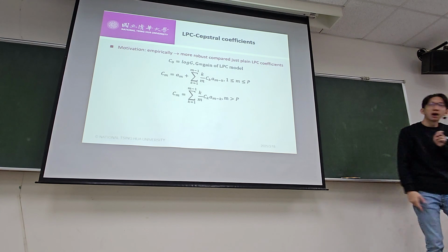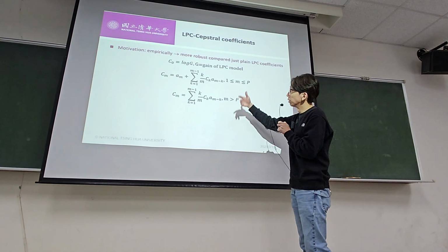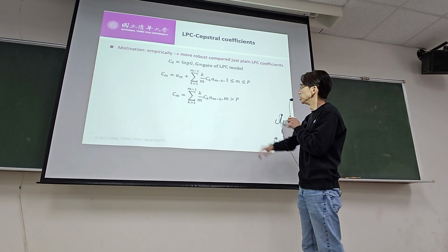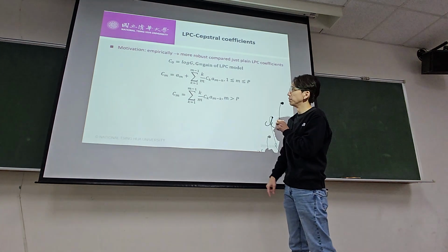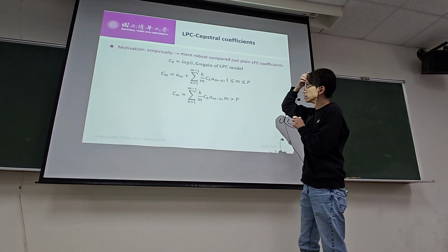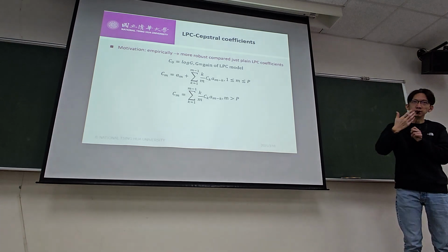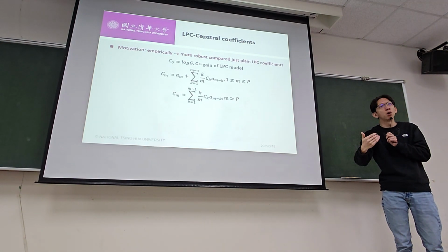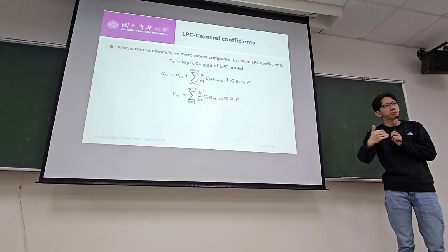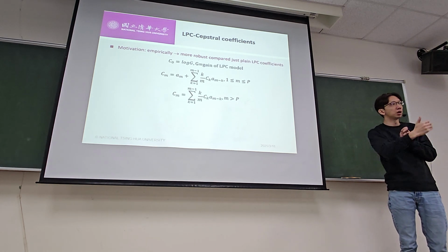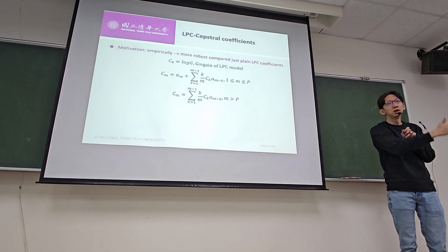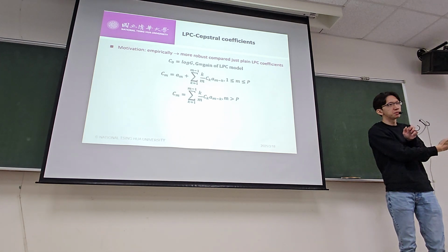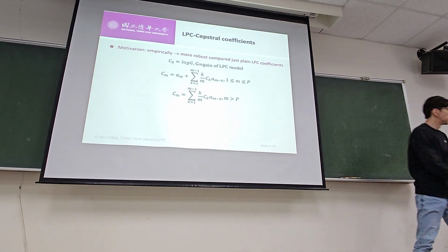Then once you have that LPC coefficient model, you plug it in to get the LPC cepstral coefficients. Depending on whether you're within p or outside p, you get coefficients like this. This is the inverse z-transform of log H of z, where H of z is that all-pole model, with the alpha coefficients coming out from the Levinson-Durbin recursion, computed from the autocorrelation function on the segment of the window you chose. So basically that entire set of steps gives you the LPC coefficients.